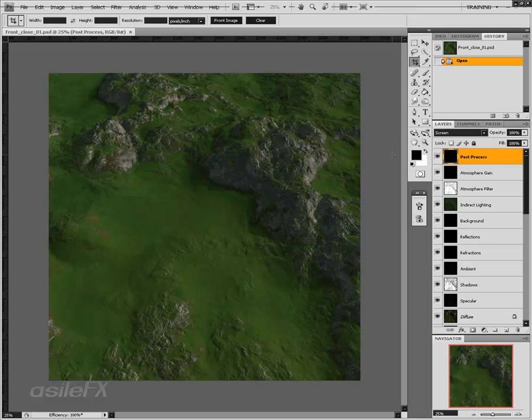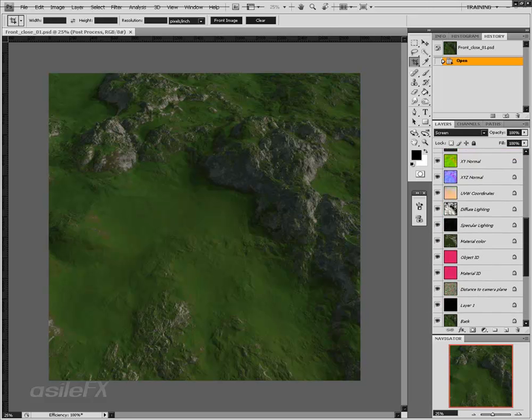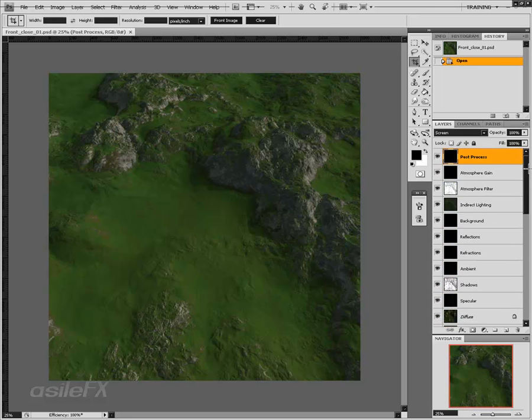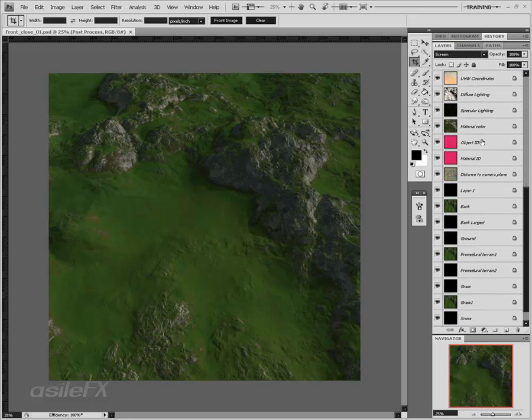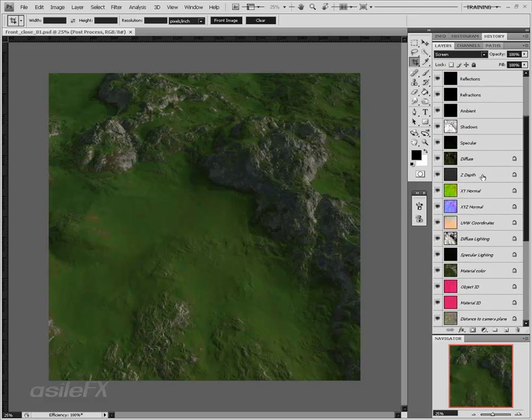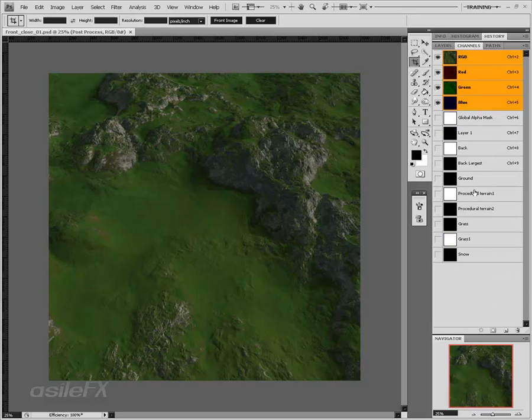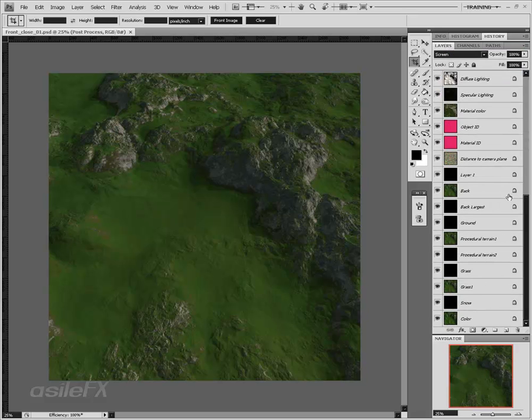with the multipass, where I've enabled several of the multipass options, and we can see in Photoshop that we have all the layers for everything that was selected. And if we go over to channels, each of the layers will also have a lot of the masks available. Now, in this case, some of the masks that were checked didn't render. One would be basically the materials, where normally we would have a mask for each material layer.